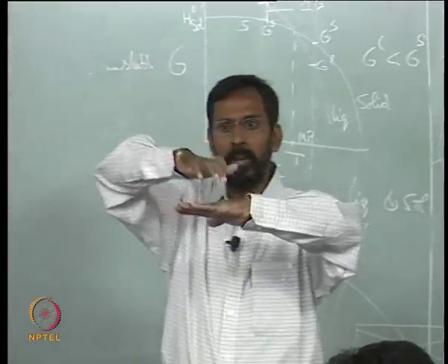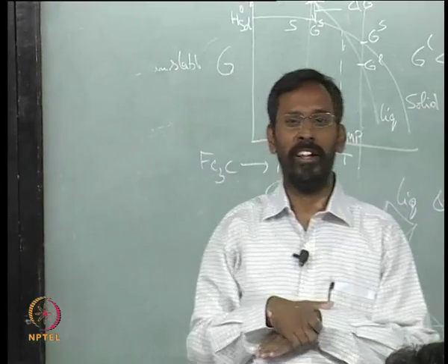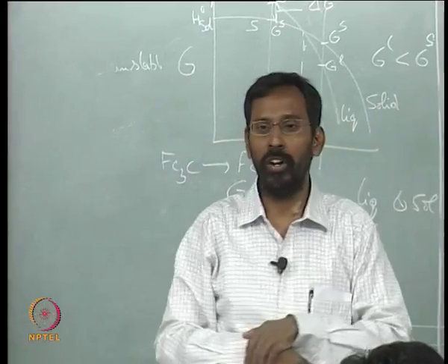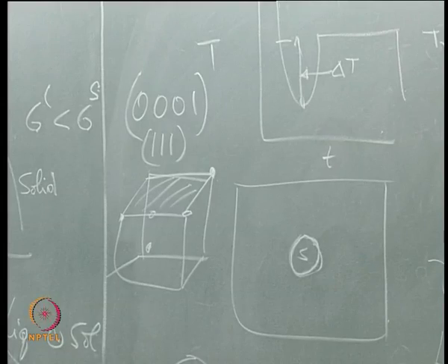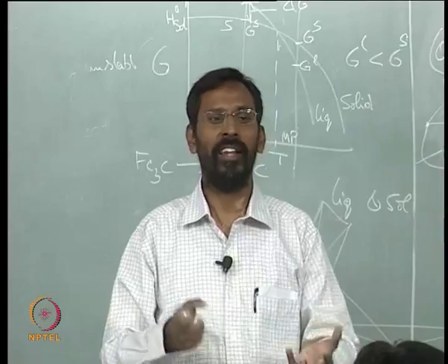So, the aluminum can nucleate on that particular 0001 plane of titanium boride very easily, with its 111 plane parallel to the basal plane of the TiB2, and then the nucleation can occur.